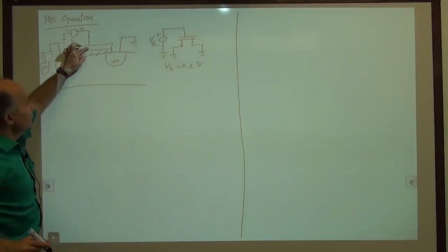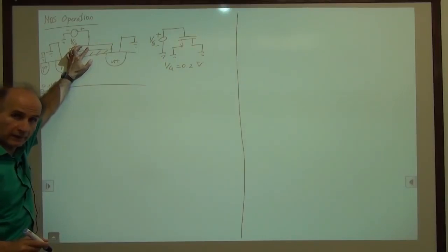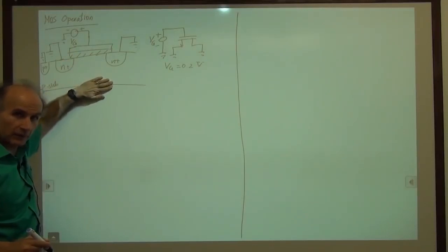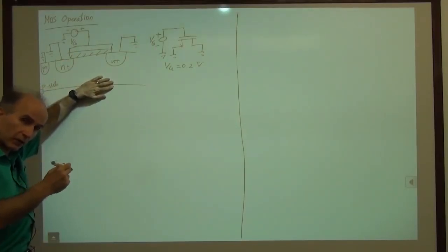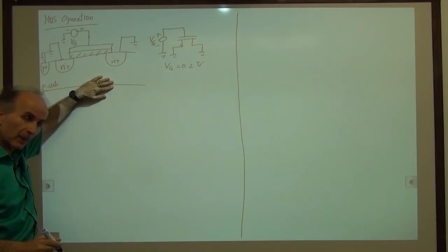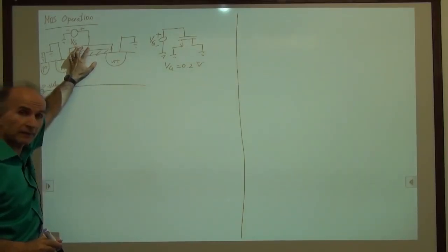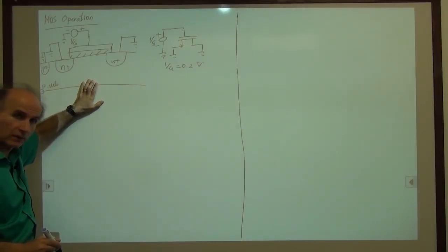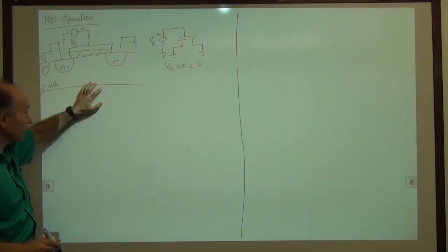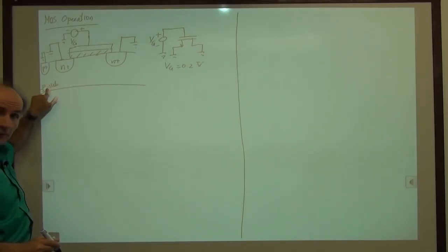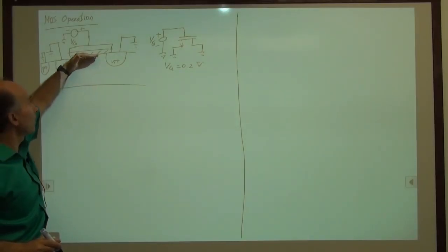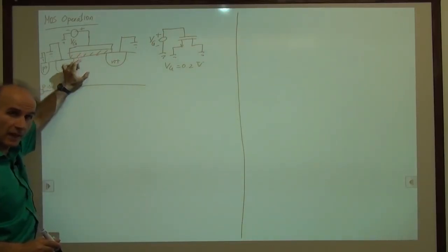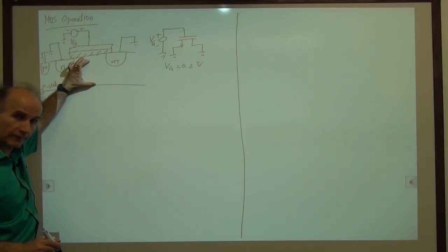All right, so this voltage is becoming more positive. And we still recognize that we have a capacitor between this plate and this plate, like the simplified structure I showed you earlier. So as this voltage becomes more positive, it wants to repel positive charge here. Do we have positive charge? Yeah, we have some holes. This is a p-type material, right? We have some holes. So the holes go away from this interface between the oxide and the silicon, the substrate.